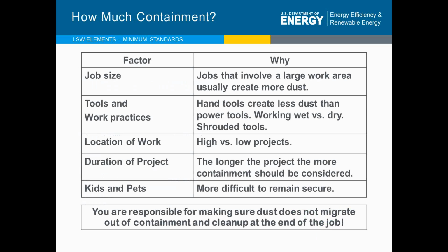How much containment? It's really up to the certified renovator. This is the call of the certified renovator. And it's going to depend on a lot of different criteria. Some are listed here. The size of the job. Obviously, if you're impacting the entire exterior of the house, many rooms interior, that's a larger job than just simply drilling a few holes in the siding or interior. So logically, it makes sense that the larger the job, the more containment.